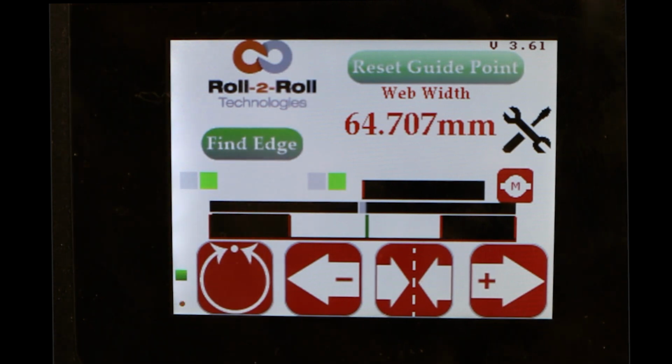So if you had a sensor that is double the size, like 221, the output would be 64 divided by 221 times 10, and that's going to be close to about 2.5 volts. That's how the output is scaled.